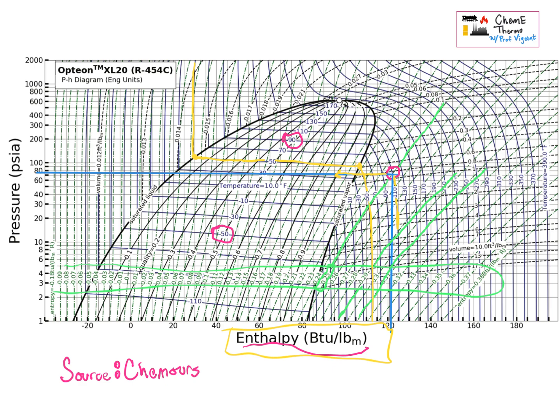And I want to add one small thing that I realize I omitted because I don't happen to use this, but I do want to call your attention to the fact that I'm going to highlight this. Volume is also captured on this graph. So if you need the specific volume or density, just flip it over, you can also find it here. And that's going to be useful in your design if you want to figure out how big your pipe's got to be.